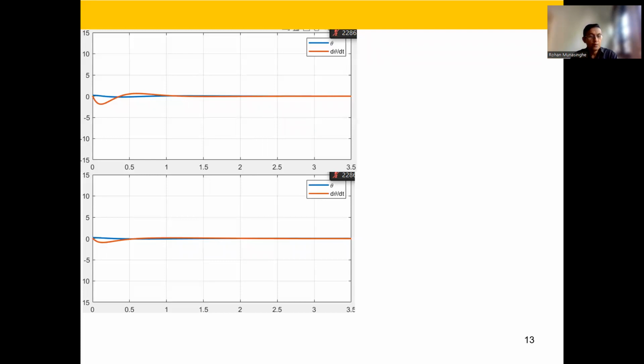So we already see the control performance, right? LQR is better than the state feedback controller, because as you know, with state feedback you have to assign the poles, and you don't know whether these poles are the best positions, but you set them to get some reasonable performance. But LQR is an optimization process, and you calculate the gains in an optimal manner, if you set your cost function properly,